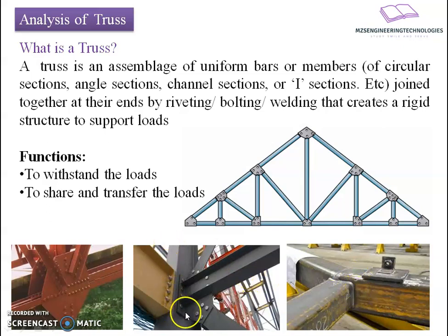Again, if you go towards the middle picture, there is a connection made with a metal pin which has threaded ends that receive the nut, and after tightening it produces a clamping force and thereby secures the connection. Such a type of connection is called a bolted connection.